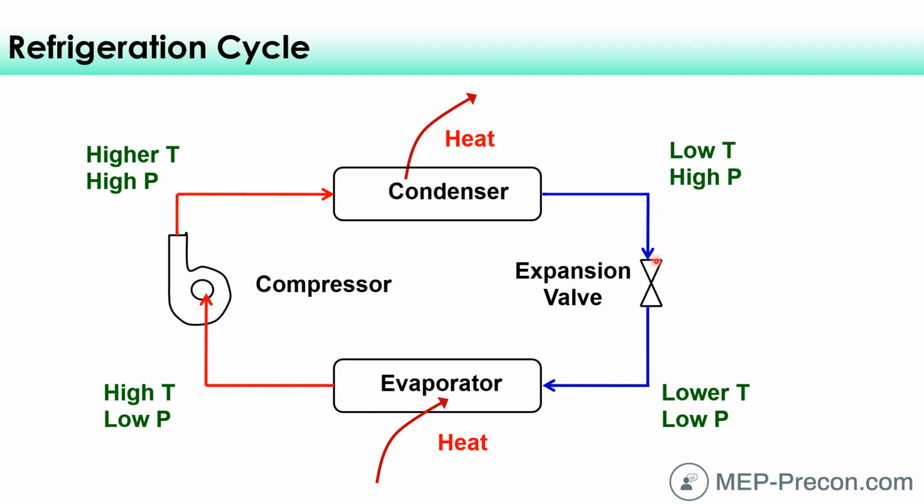So the refrigerant goes through that same orifice. And this is just like that aerosol can, that psh, psh. When you feel that and it cools down the can, it's going to cool down that refrigerant to a really, really low temperature, back down to about 30 degrees and a low pressure. So that's how we get to our low temperature, low pressure refrigerant.